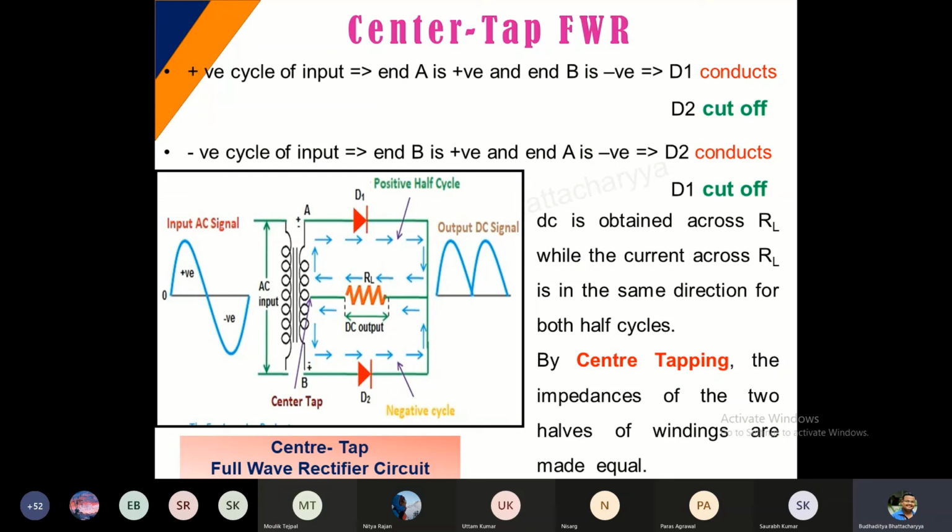To be honest, that can also be achieved using a capacitance in parallel to the load resistance. Usually, in this circuit, a capacitance is added. What does the capacitance do? If time permits, I would have shown you, but there is very little time devoted to this topic, so I might show you in the lab itself. If the capacitance is placed parallel to the load resistance, during a positive half cycle the capacitance will charge, and in the negative half cycle it will start to discharge.